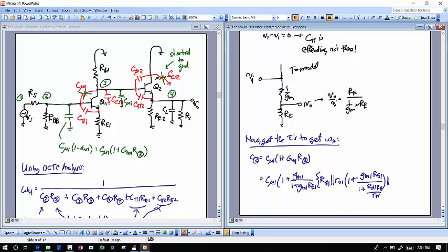But watch what I do at the very end of this. And then I got one more resistor because I got to look out forwards too. I got to take into account the loading from the next stage. So the loading from the next stage looking into the base, what's that? Yeah. R pi 2. Yep. All right.